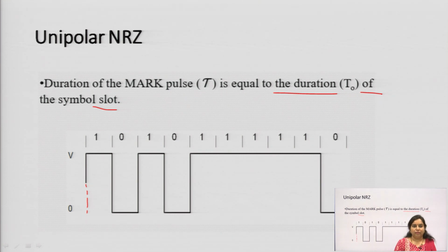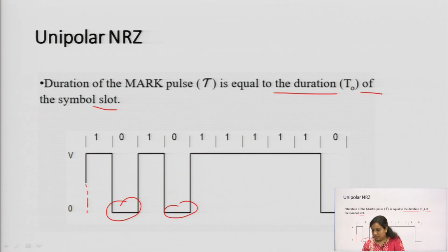Now, the main disadvantage of using the line coding that I was talking about is that if I am transferring 10 or 15 zeros continuously, the synchronization between the transmitter and receiver may break, and that condition will occur in this unipolar case only, because for 0 bit I am not transferring any data, this will be 0 volt. So, let us say 15 zeros are there in a row. So, 0 volt will be transmitted for 15 bits. So, this is the main problem of unipolar signaling.